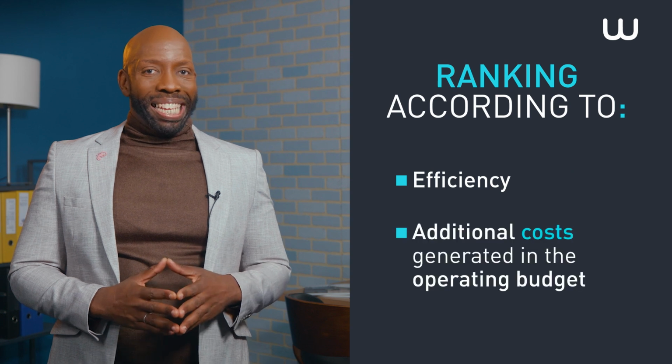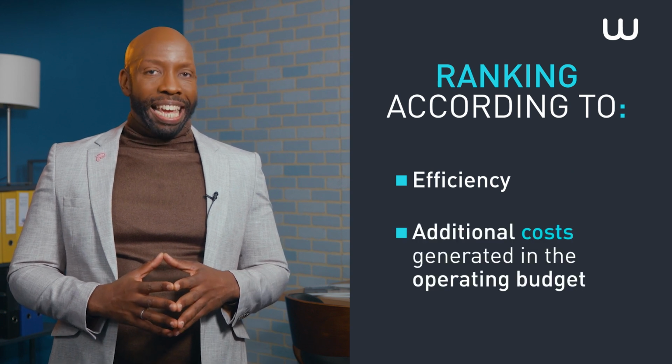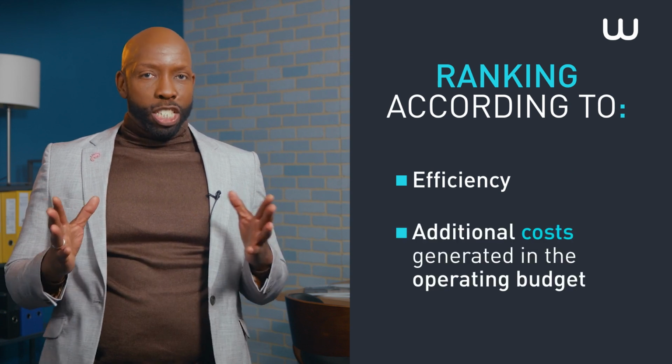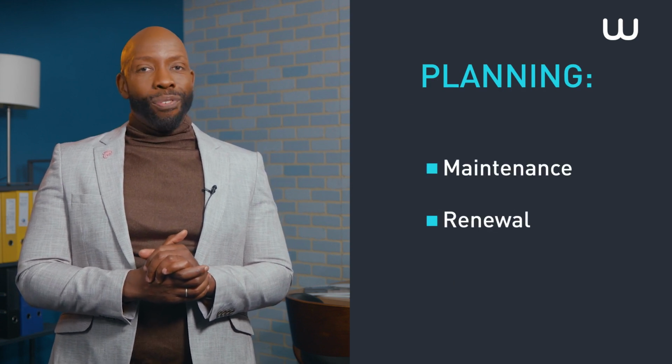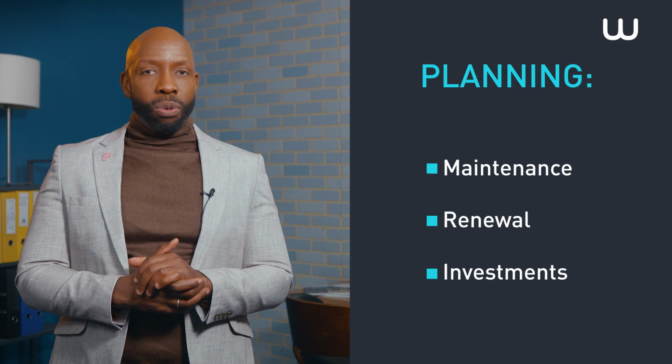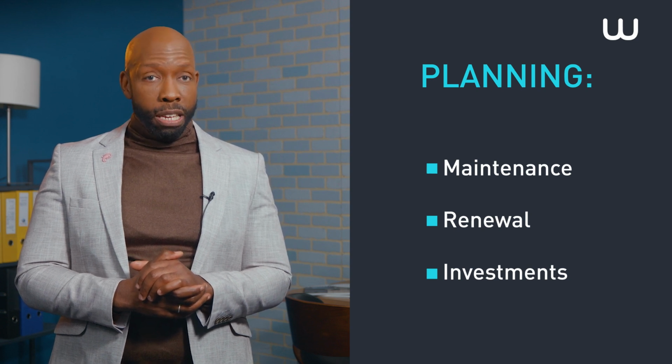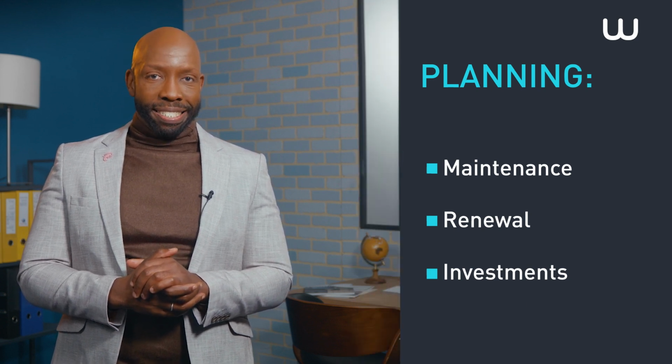Once all the electric pump units have been evaluated during an energy audit, they can be ranked according to their efficiency, but more importantly, by the additional costs that they generate. Now, this ranking helps in properly planning maintenance and renewal operations, as well as investments which must be done to improve the energy efficiency of specific sites.